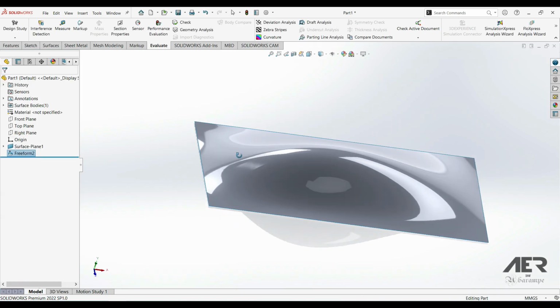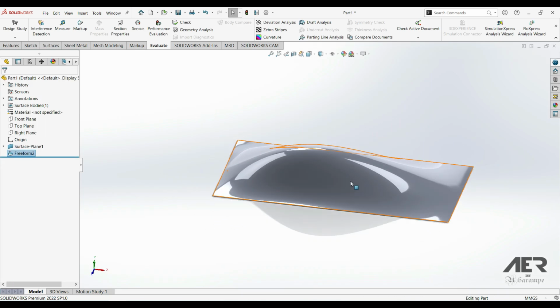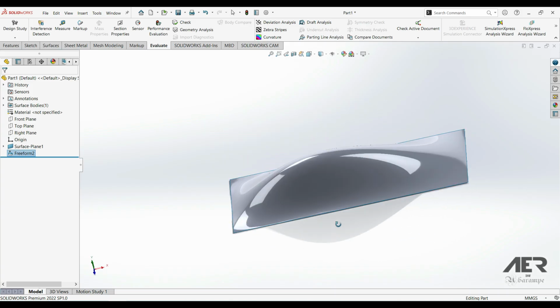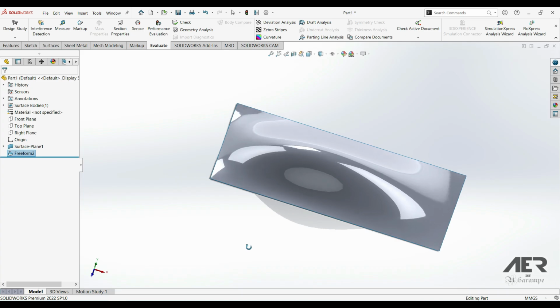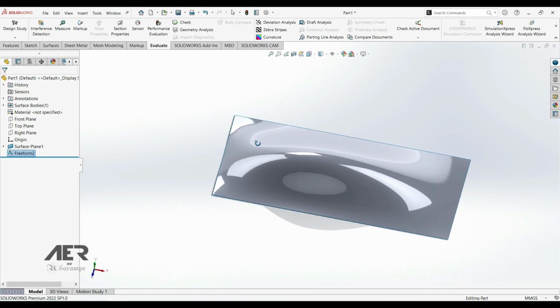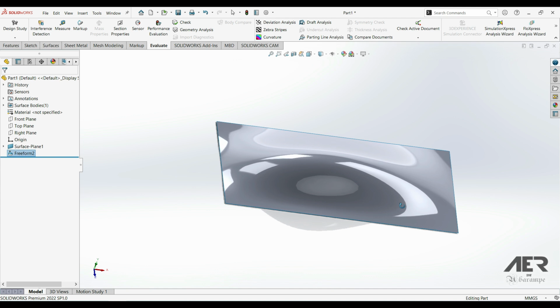So that is the freeform tool. It's potentially a very powerful one. What we do is select the surface. This can be the face of a solid or a separate surface. Then we add those control curves, which are lines along the surface. Then we add control points on those curves, and we can drag those around or adjust the values and use those to deform the surface.